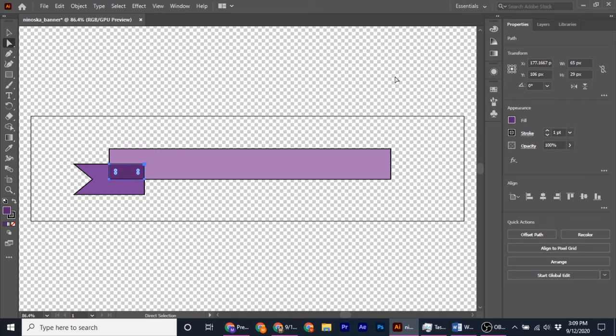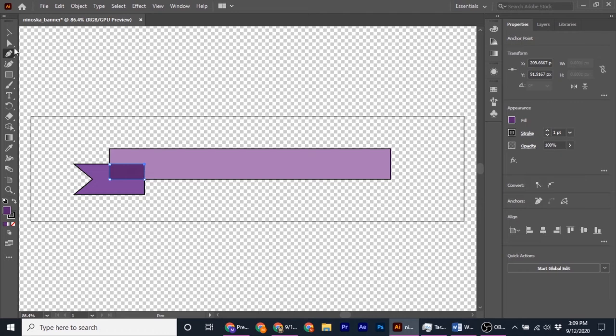So then it tells me to select the direct selection tool and select the following anchor point for the third rectangle on the bottom right. Then it tells me to drag the anchor point down until it meets the bottom right corner. So this is the anchor point that I am trying to move down. Sometimes you will notice that it is very hard to select the anchor point and move it down. When that happens to me, I usually add a new anchor point and select it and move it down.